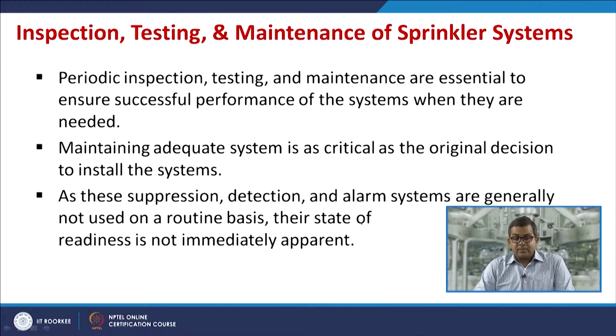So once you have installed these sprinkler systems, there is a requirement of inspection, testing and maintenance, and there is a regular protocol for this. You need to go for periodic inspection, testing and maintenance, which is essential to ensure successful performance of the system when needed.